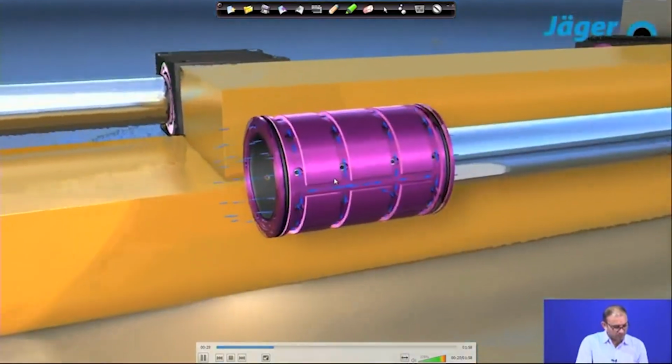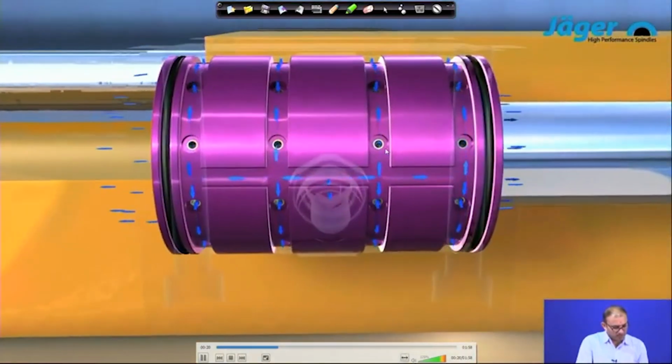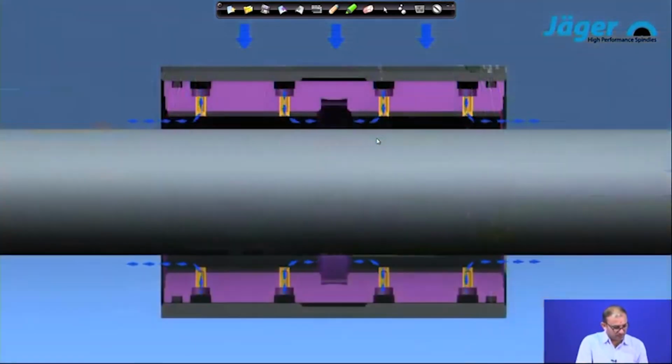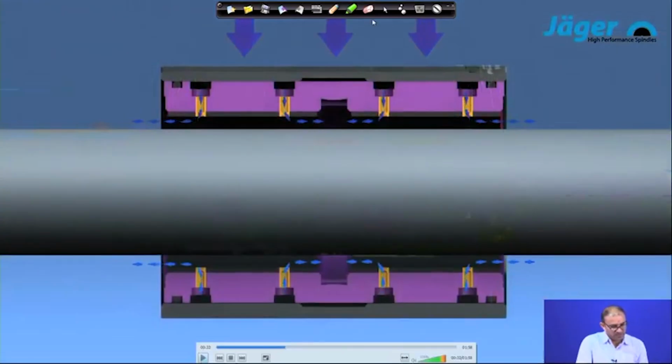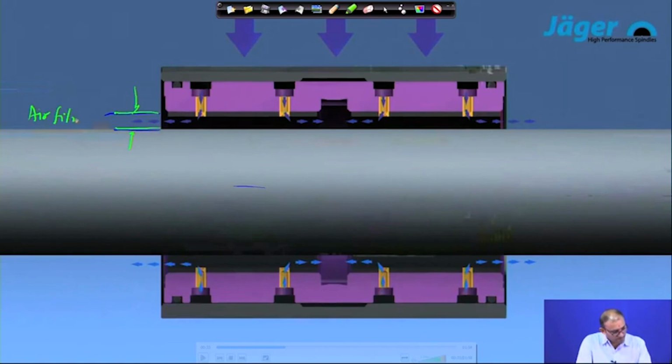So, this is the bushing and from here what we are providing? We are providing air in this particular interface. So, now this is the interface. This is the shaft and this is the bearing and in between this is the fluid film. This is called air film, and that is the same way in this direction also, correct, because we have to keep this shaft in the central position of this particular part.